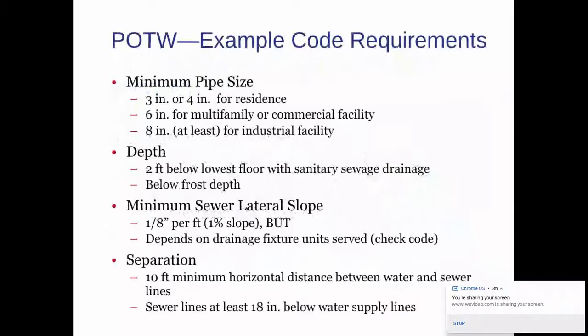Well, after that, once it's used, it goes into the drain. These pipes are a lot larger. They're inch and a quarter, inch and a half, and once they all collect together, once they start leaving your house, or like the mains that are in the walls behind the sinks, they get to be 3 and 4 inch diameter pipes. If they're in a multifamily, like an apartment building, they might be 6 inch, or if they're in an industrial facility, they might be 8 inch.